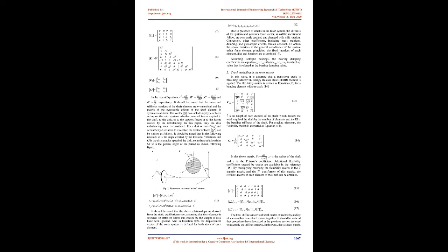The wavelet energy package is used to better locate the crack. The presence of the crack has led to changes in the dynamic behavior of the rotor. The 1x and 2x harmonics of the steady state response are important parameters in the diagnosis of a cracked rotor.